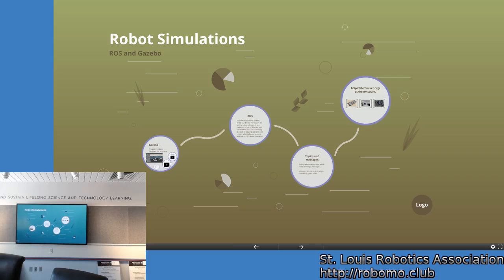Also, it's great for repeatability. Say I have a vacuum cleaner robot, and I want to ensure that it can get around a certain obstacle every time. I can set up a simulation with a certain type of chair that maybe has thinner legs, and maybe another simulation where it's going under a table that's not quite tall enough, which I find it gets stuck on. And as I update the software, I can rerun it on all these older simulations and verify that my new changes to fix some new problem didn't break some old problem that I used to have, without having to manually test the robot.